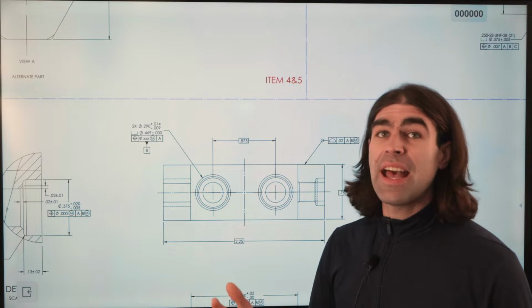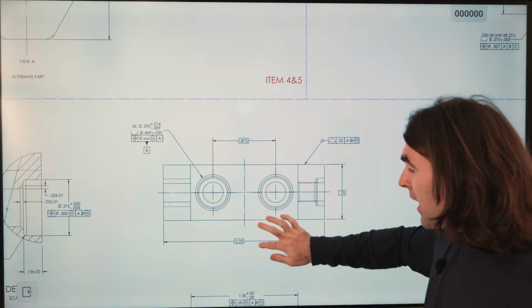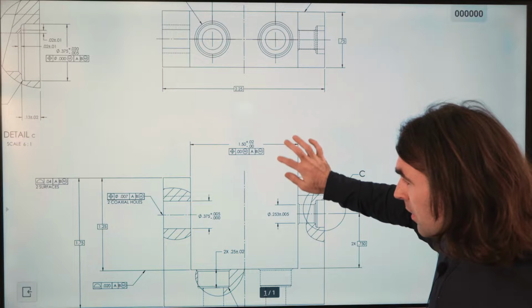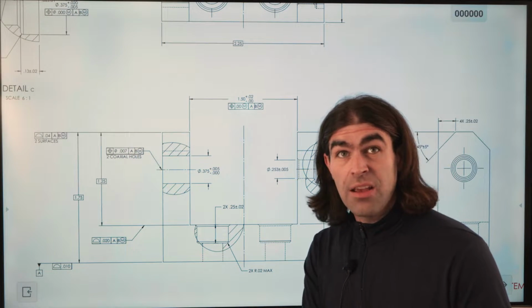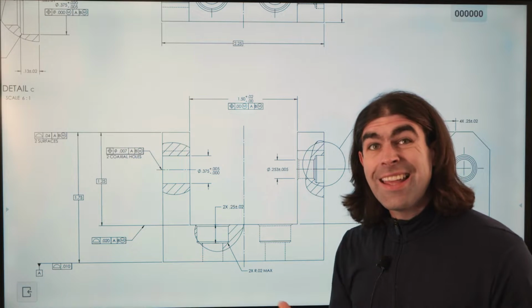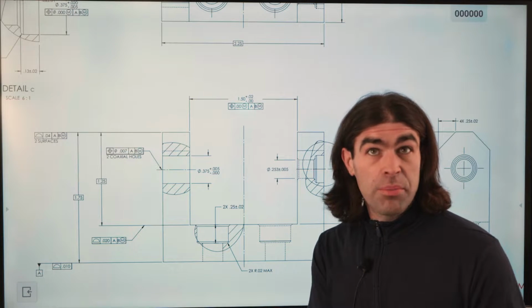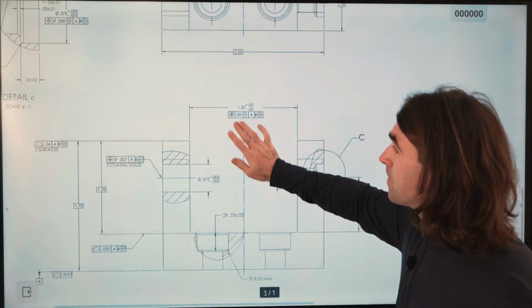You get less stack-up when you do it this way because of the holes and the planes, so this datum A is mating up to datum A of the base plate we were just talking about. The two holes in each of the two parts line up, they're both datum, so you don't get any stack-up between all of this stuff.